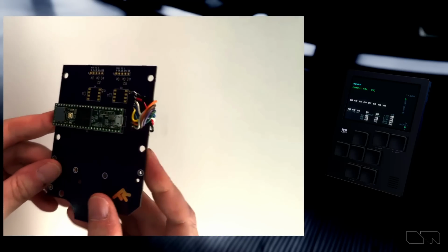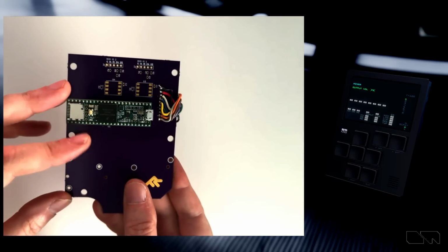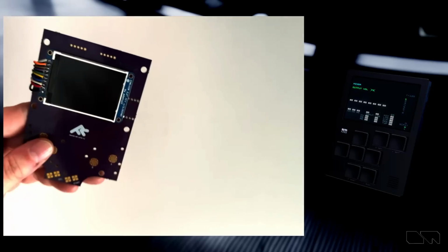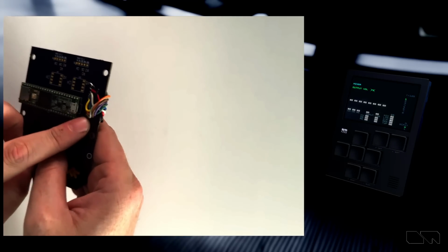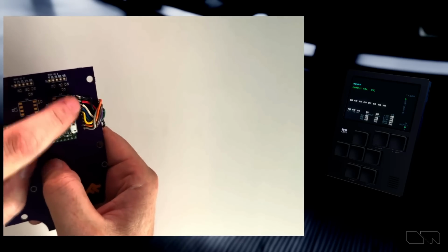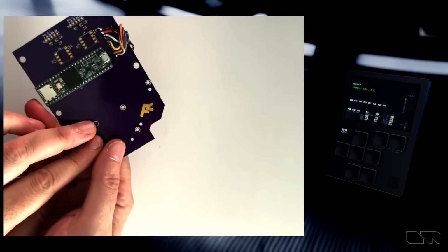You could also see this is funny. You could see this amazing set of wires here, and that's because I did the pin layout backwards. I wasn't thinking about this screen plugging through the board to get to this side. So all of the wiring is here in the circuit board, but it's all backwards. So I had to redo it all with manual wires around the thing. It was just a bad prototype on my end.